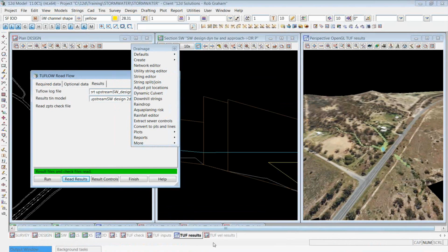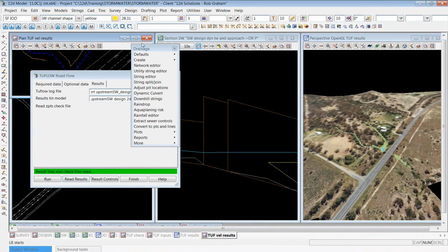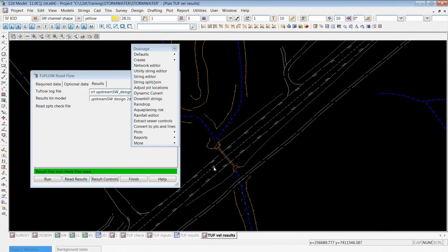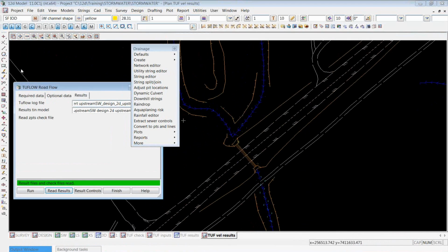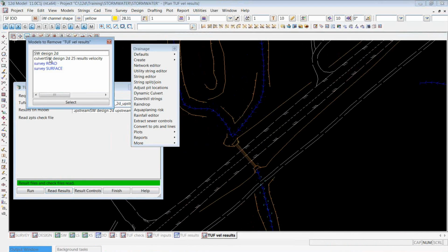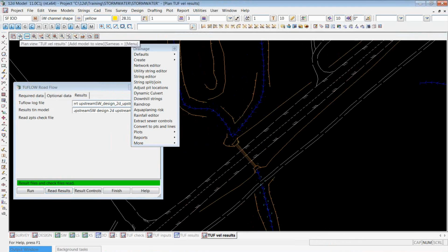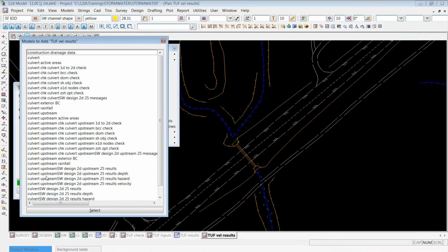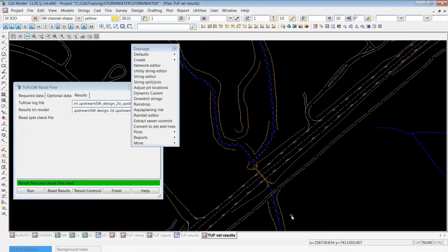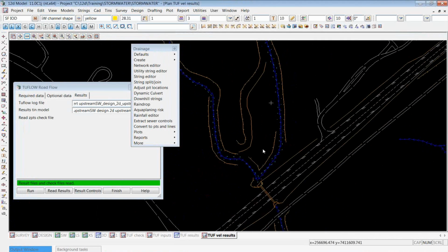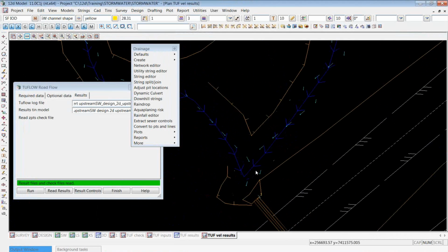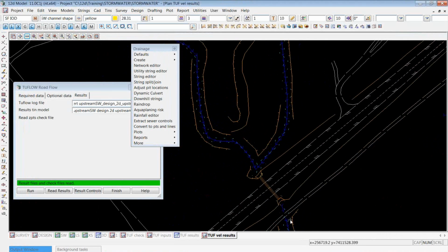Now, water levels and depths are, of course, a crucial part. One of the other issues that does become very important is your velocity vectors as well, and understanding the velocity of your flows. So if I was to come back here and turn off that first analysis, come back to the one that had the upstream and look at the velocity results, what I'd be able to see are the velocity vectors showing the water coming down that channel. When it gets deep here, they will get a little bit smaller and then come out the tail race.